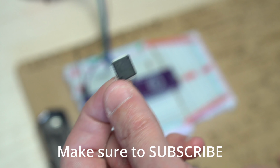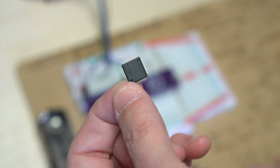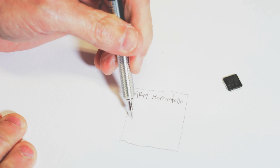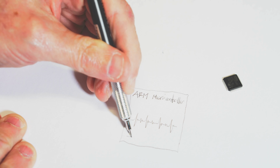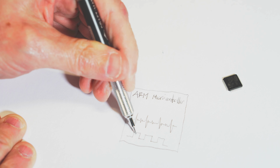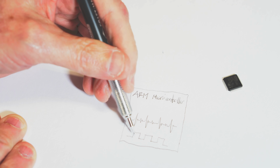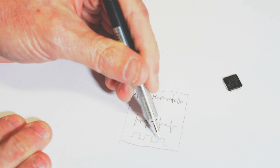In this particular microcontroller, the default speed is 8 MHz, 8 million cycles per second. Inside the ARM microcontroller, there is a pulse, very similar to a heartbeat. But the pulse of a microcontroller looks more like this. And within each pulse, an instruction is able to be carried out. Very similar to the instructions or the code that we create, but these are more low-level instructions. But you don't really need to know that. But in some circumstances, you need this pulse to be faster.